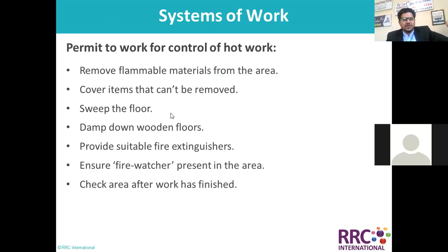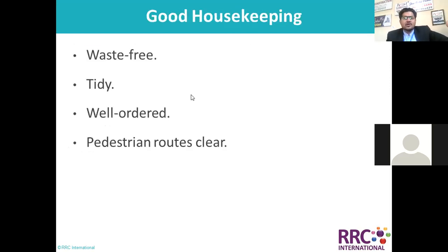Cover items that can't be removed and sweep the floor, damp down wooden floors and provide suitable fire extinguishers, ensure a fire watcher is present in the area, and check the area after work has finished. That's why the fire watcher stays for like 30 minutes even after the hot work is done. The reason is the surface is still hot, and he has to stay for 30 minutes to make sure nothing will go wrong. Good housekeeping is critical not only for fire safety, but for everything.